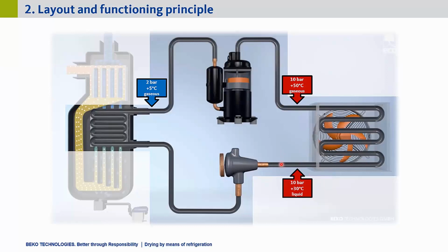Now the last important part that changes something on the refrigerant is normally the capillary tube, or here in the eco dryers it is this electronic valve. So the capillary tube creates another cooling effect through expansion because of pressure drop. And this pressure drop is caused by length and narrow diameter.